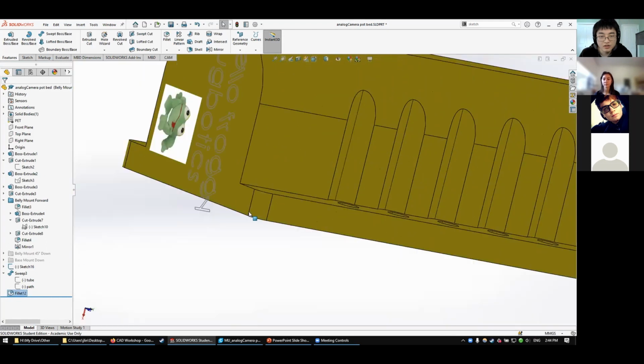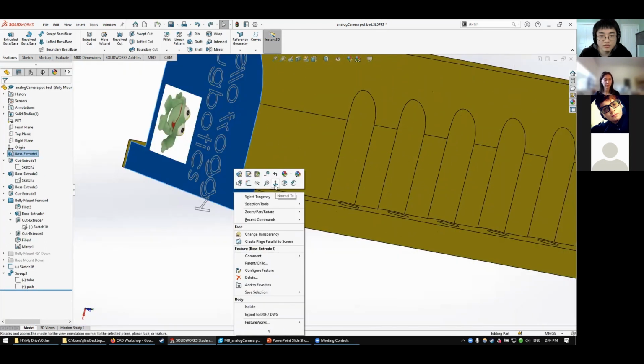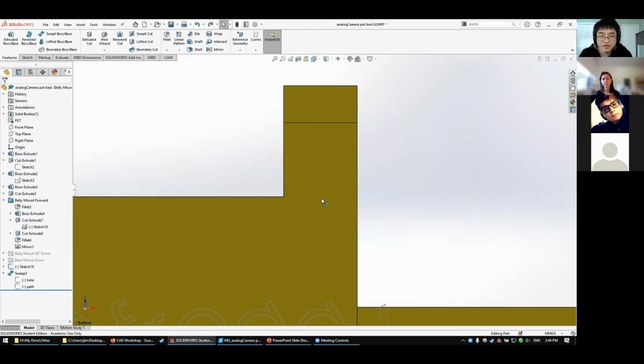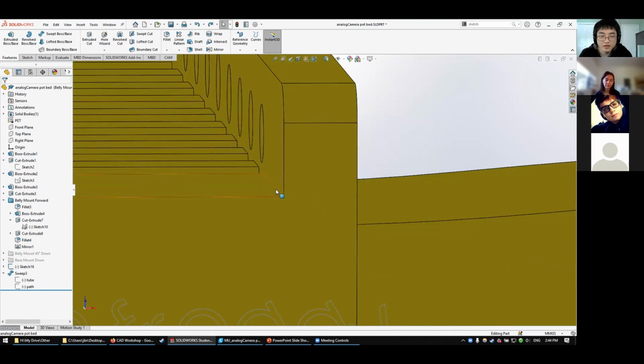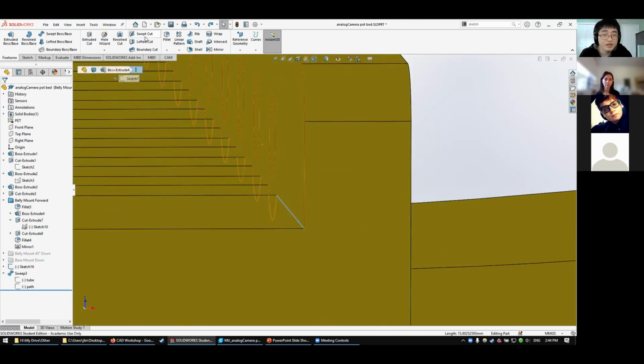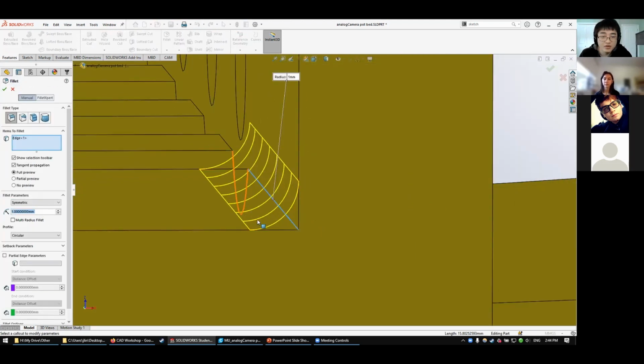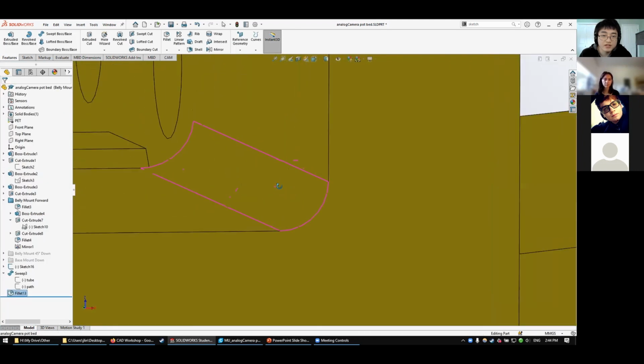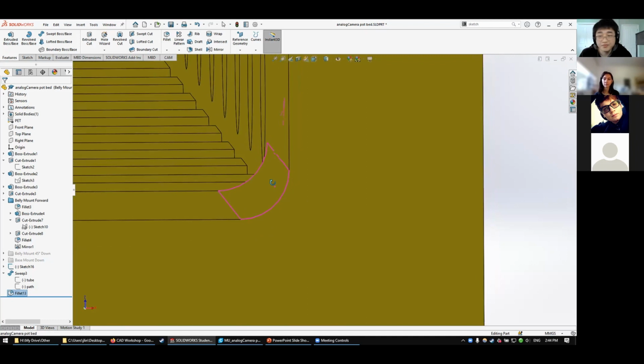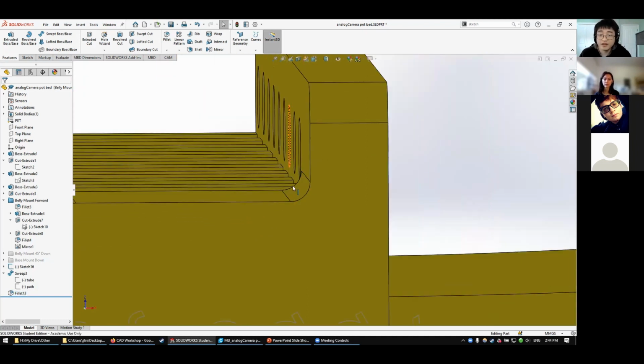So let me see if I can go normal to and zoom in. Okay, I tend to use fillets mostly for cutting stuff, but you can also use them to round inner edges. So choose fillet or chamfer, and then it will show you, hey, do you want to add some material here? And then click OK. And now we've got a rounded inside edge. So really nice, yeah. And as Naomi said, it fixes something up, makes it stronger, and looks nice as well.